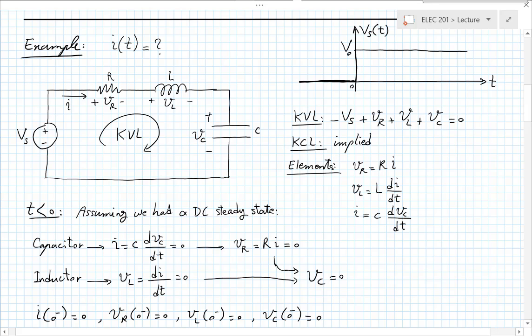So now you have an inductor with that voltage. Okay. Now, if an inductor has a voltage, what does that say about its current? It has to change, right? Because V equals L di by dt. An inductor can't have a voltage and keep it there without any change in current. Now, the current in the circuit at that moment was 0. But the inductor says, well, you forced me to have this voltage. It means I'm going to have to change the current. So the inductor will start forcing a current through the circuit.